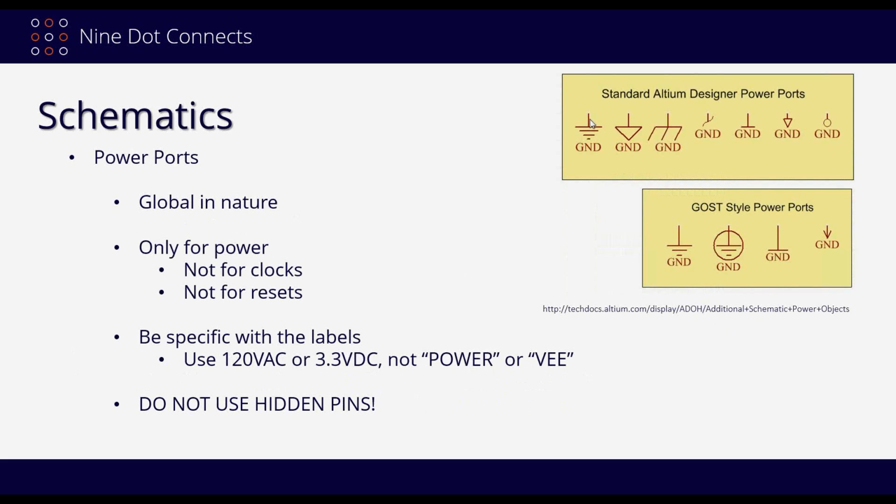Let's talk about schematic ports, power ports, for a moment. They are global in nature. They are only for power. You don't really want to use them for clocks and resets. Now, can you in something like Altium? Yes, you can. Why should you not do that?